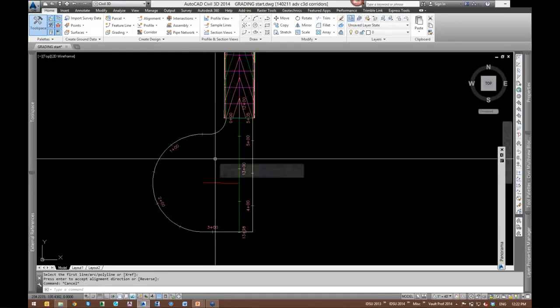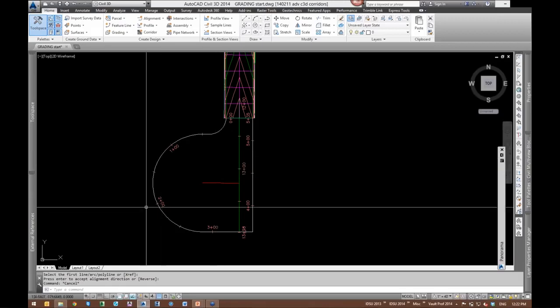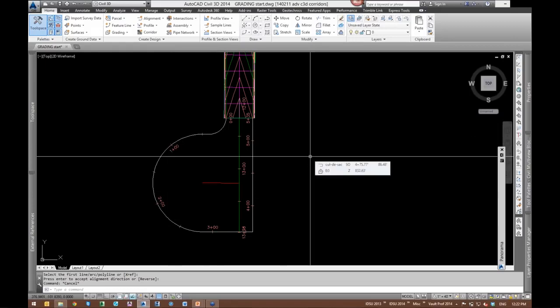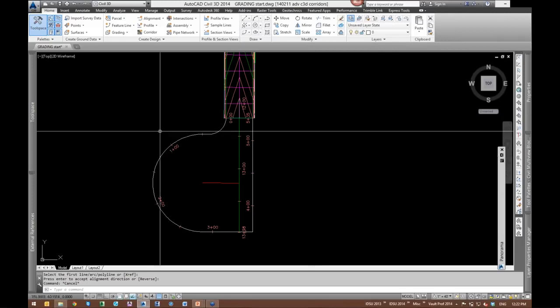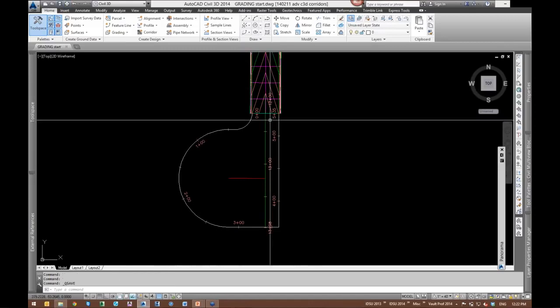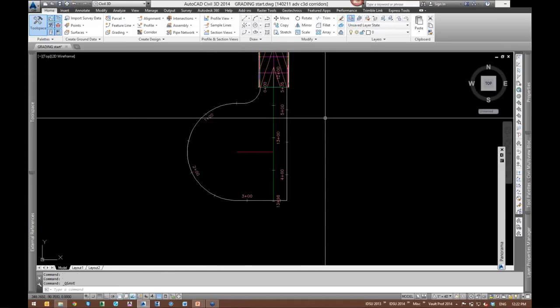So you want to spend your time on this auxiliary corridor generating that auxiliary surface so that your surface profile is quite simple. Some of you have used the drainage concept in parking lot grading. This is kind of building on that same concept, but it's almost even better than that because the drainage surface is built on the exact same alignment and profile as the actual corridor model. So it's even more dynamic than using some feature lines and grading tools and the whole drainage surface concept in parking lot grading.